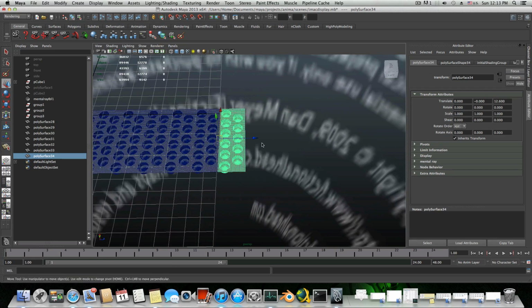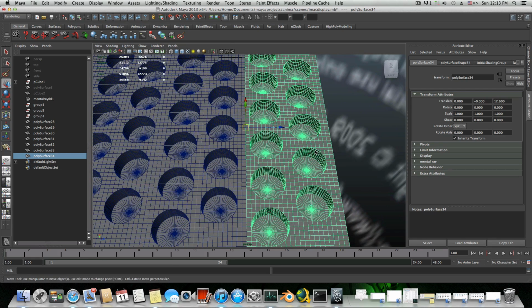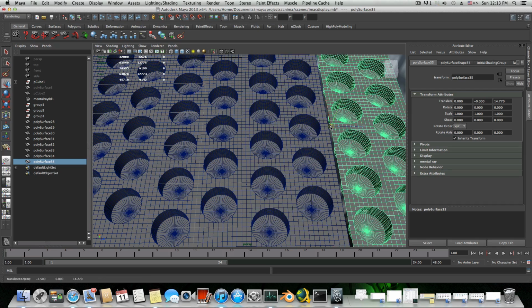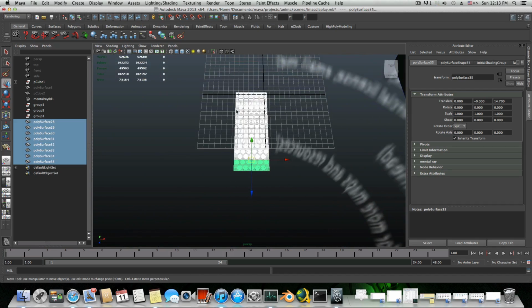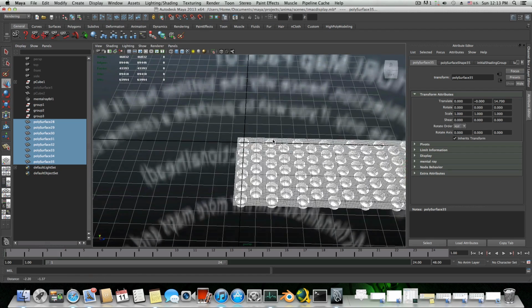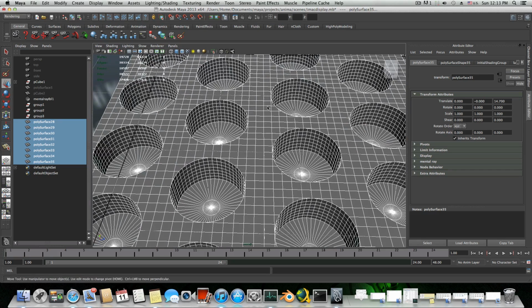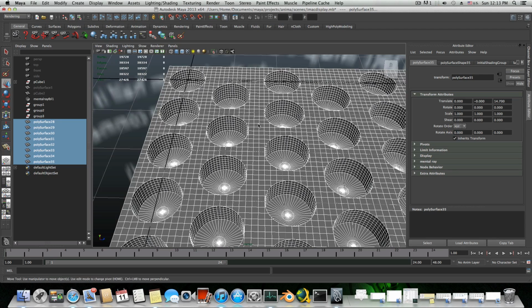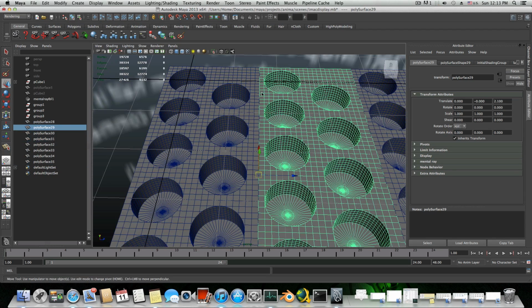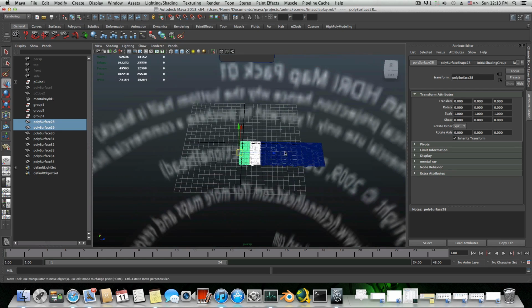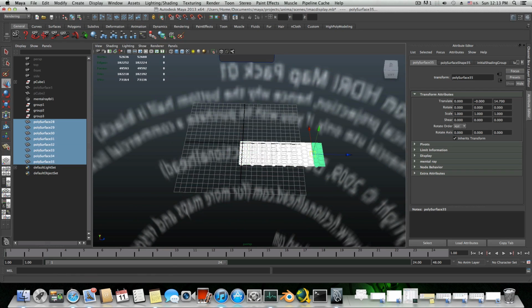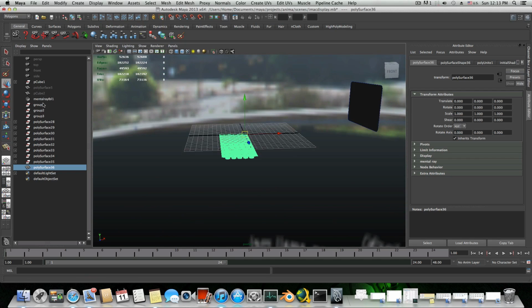Now Control D and snap it over here, V. Now you can do the same. What I've done earlier is just make sure that every two rows, every two lines of holes, you grab the middle vertex line here in between them in order to attach them. Okay, here, this one. So grab them both. First grab them all together, Mesh, Polygons, Mesh, Combine.